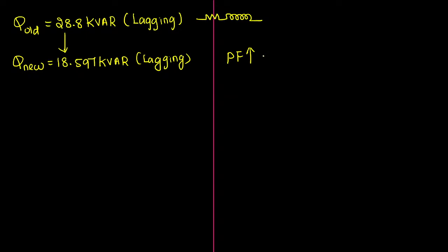Actually, when will the power factor become 1, you assume and see. Power factor will become 1 when the total imaginary part of the circuit will be equal to 0. What is the conclusion? The imaginary part is the reactive power. So as the reactive power value decreases, the power factor value goes closer to 1, that is the conclusion.